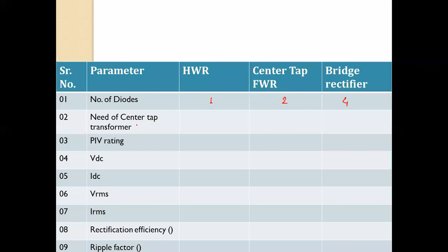It's the need of a center tap transformer. Is the center tap transformer required for the half wave rectifier circuit? Absolutely no. Is the center tap transformer required for the center tap full wave rectifier circuit? The title itself gives that it is required. And is the center tap transformer required for the bridge rectifier circuit? So it becomes no.